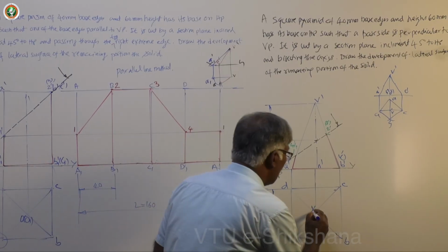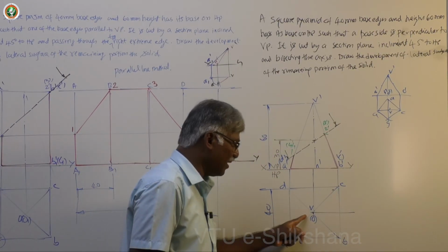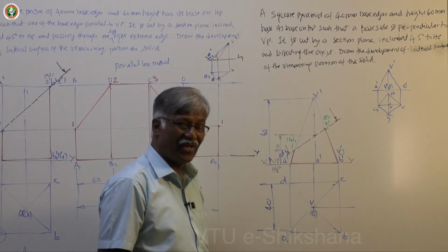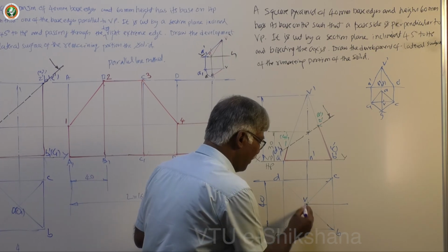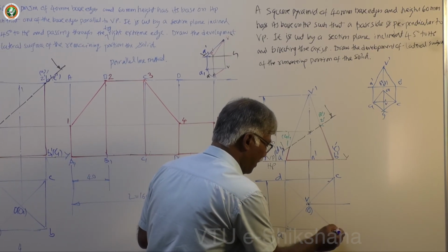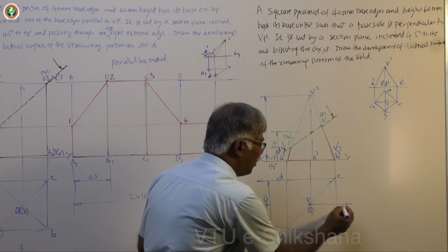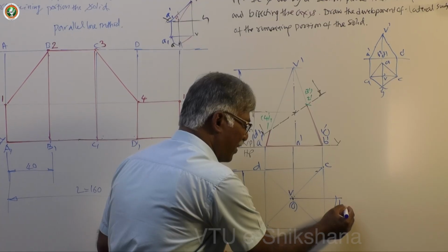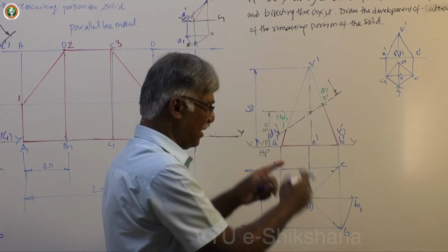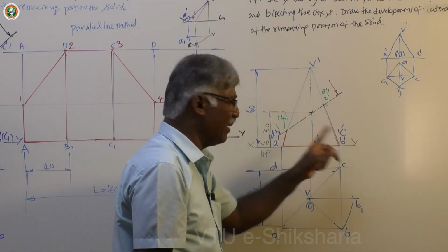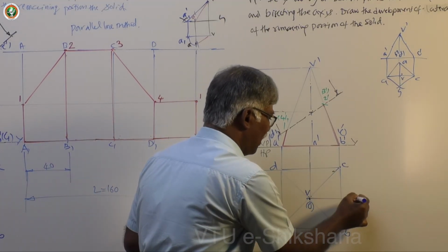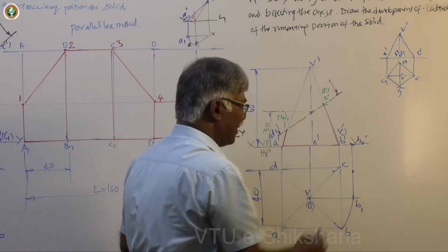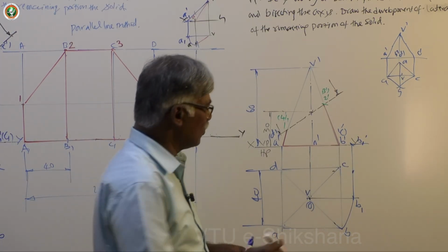What I have to do is, here with V as center, I am calling it V, not O. Actually, that is VB. VB is the reference for me. With V as center and VB as radius, in this figure, draw an arc. That means we are making it parallel to XY. This is B1, because I am anticipating B1 dash there. Any name you can give; you can give BM, then BM dash. That's all. Next comes project it and get, on the locus of B dash, B1 dash. That's the convention we use in straight line problems.